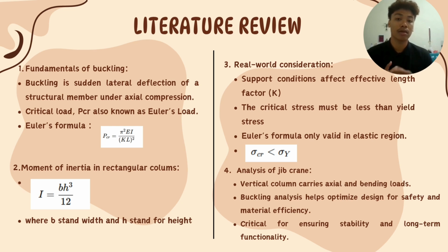Third is real-world consideration. Support conditions affect the effective length factor, which is K. The critical stress must be less than the yield stress. The Euler formula is only valid in the elastic region, where the critical stress must be less than the yield stress.